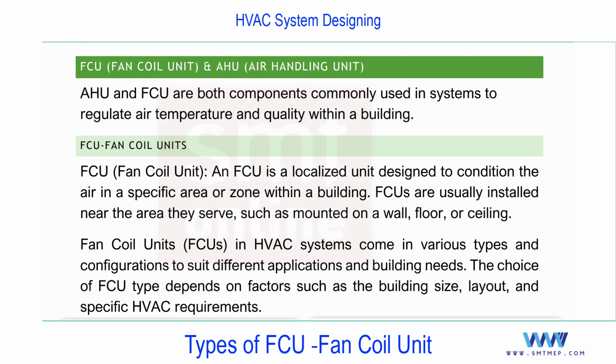So the refrigerant system we already discussed, the vapor compression cycle, along with the different systems. Chilled water system you'll find in district cooling system as well as in chillers, air cooled and water cooled, in detail. And then the next is the air side system. In the air side system, you'll find this AHU and FCU. And again, if you talk about the air side system, you'll find CAV system, VAV system, dual duct, etc. That also we'll discuss. Let me complete this.